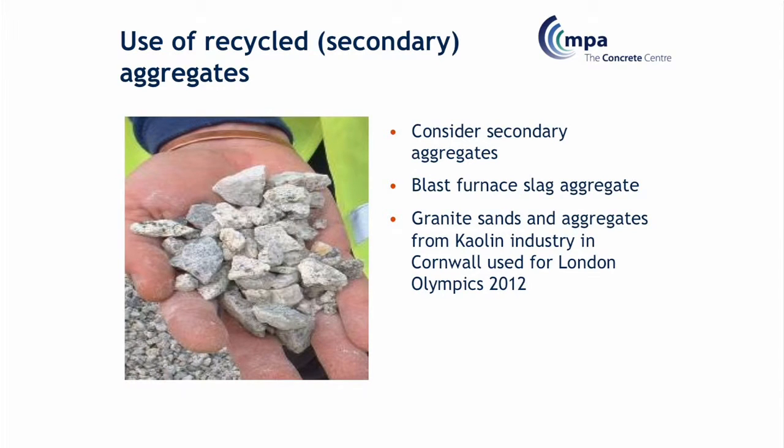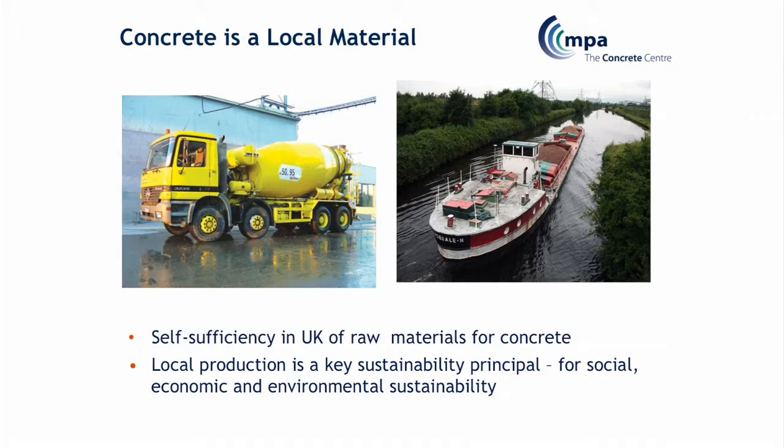There is an alternative. There's also secondary aggregates. There is a very good supply of these down in Cornwall as a byproduct of the kaolin industry, called granite sands or granite aggregates. But again, one just needs to consider how you're going to get that to your site in a low carbon way in terms of transport costs. Concrete is a local material.